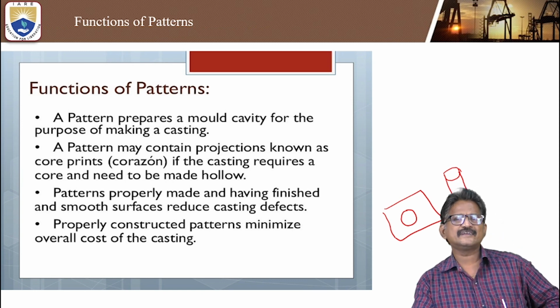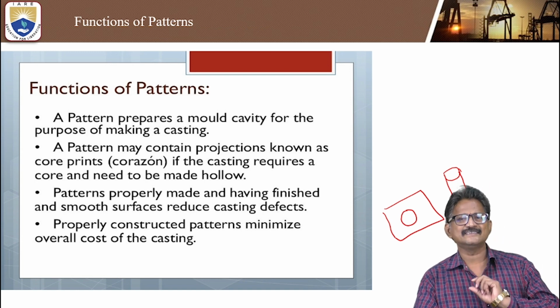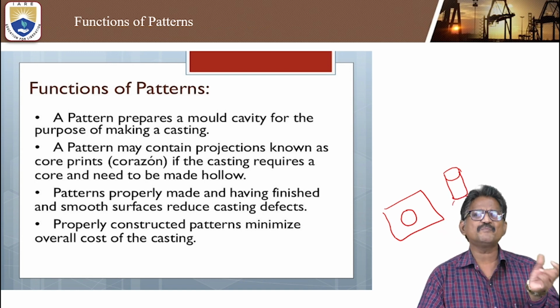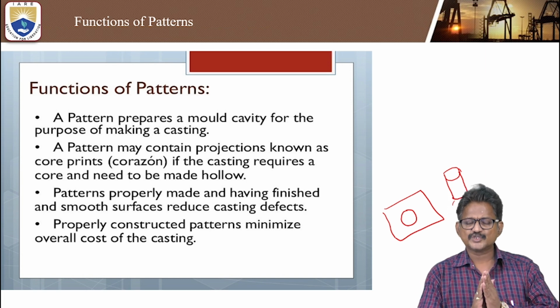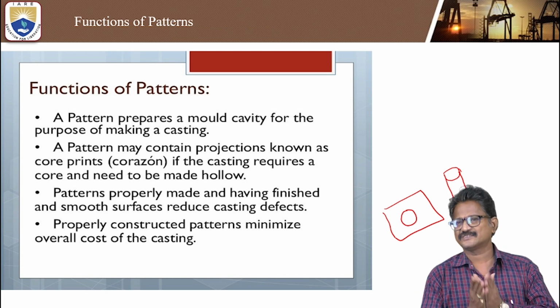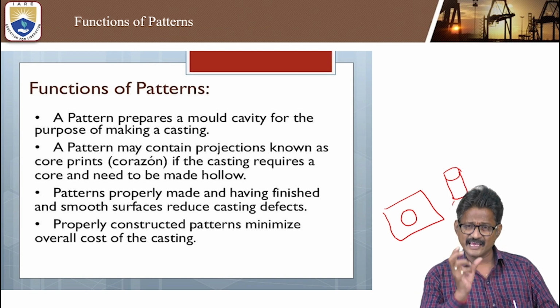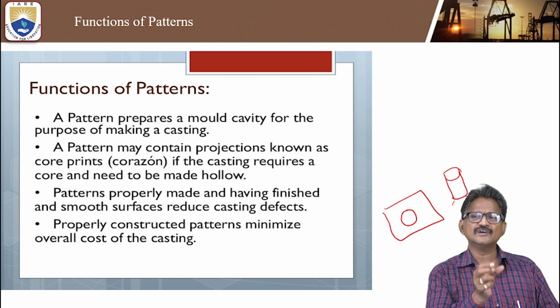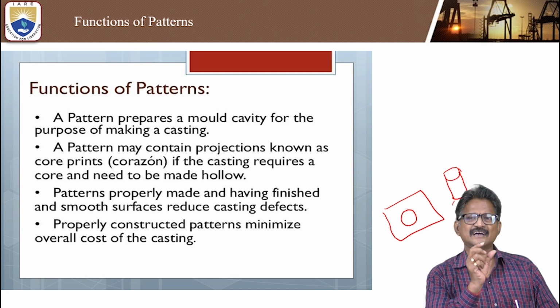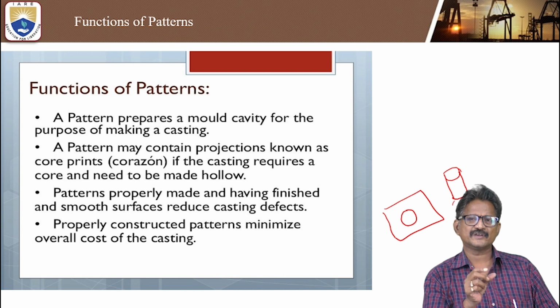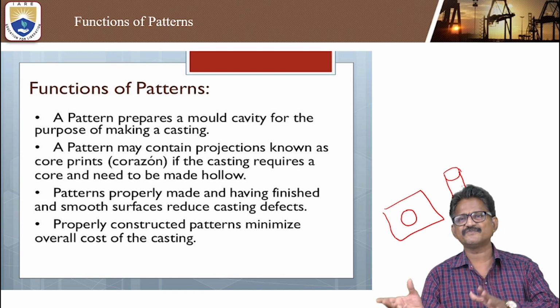Another important function of a pattern is that it can be properly made and have a smooth or finished surface. If you want to get an exact component, you should have a good, finished surface on the pattern. Then only you will get the final casting.